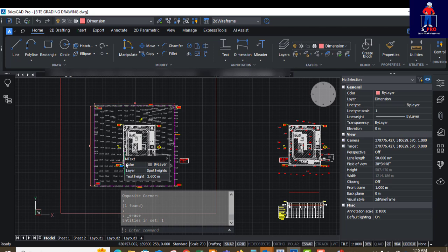So when you have determined that, you can now cut your sections, then do your profiling, choose your scale. Normally, I prefer scale 1:1 so that plotting of this profile will not be a difficult thing for you. Otherwise, you fall back to the type of scale we used in secondary school where we did quadratic equations, the plotting of graphs with quadratic equations. But if you use scale 1:1, it's not going to give you a headache.